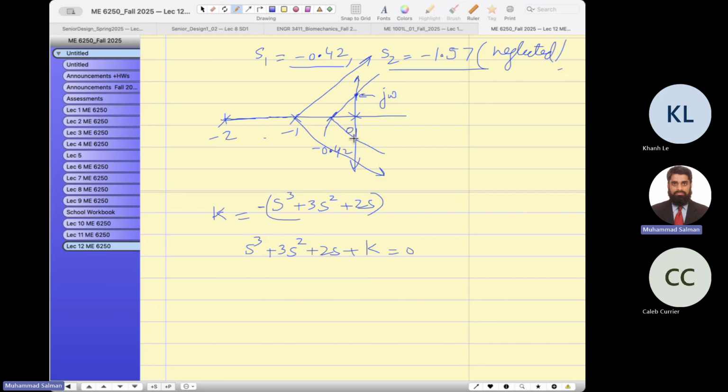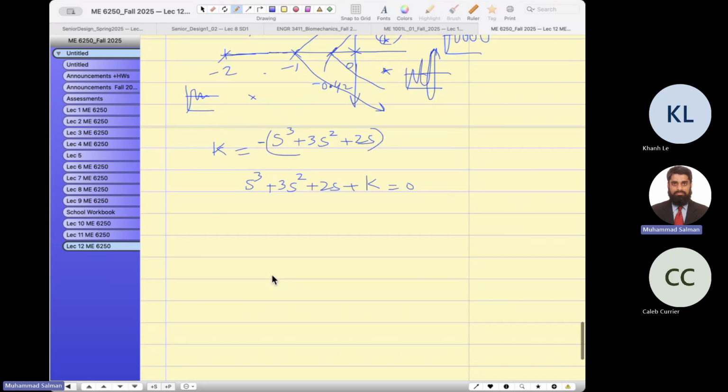And now you plug in, since we want to find the location of this point, and the response over here is undamped response. So you see, undamped, no damping. If you see over here, the poles are located here. This is known as the unstable system. It keeps on growing up and up. And if the poles are located somewhere here, the response will be going up, and a very nice response. It comes to the mean position, which is the stable position. You agree with your professor?